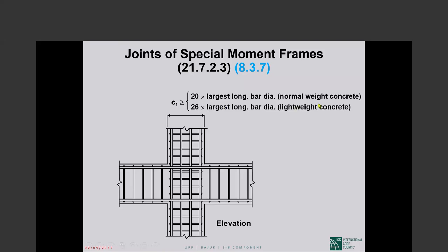That one is probably not important for you. Now when this condition is violated, you do not go for larger columns, you go for thinner bars. Okay, so the column dimension, this is interior column dimension, shall be no less than 20 times the largest longitudinal bar diameter.